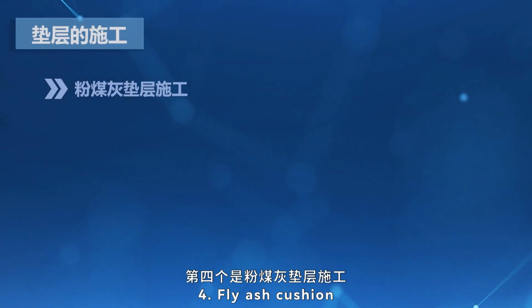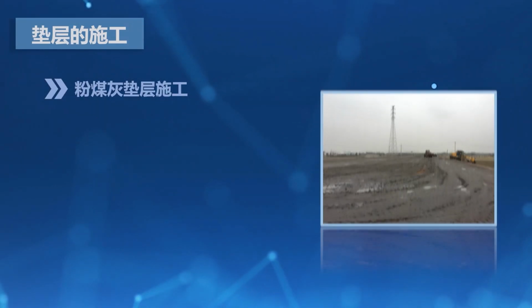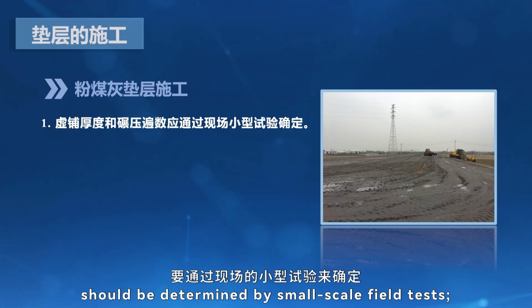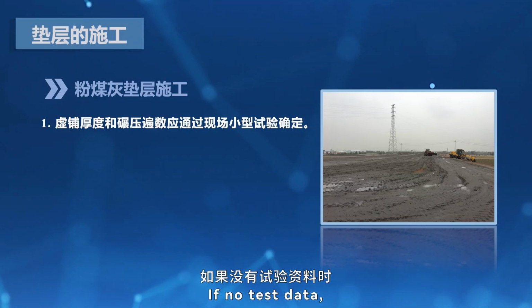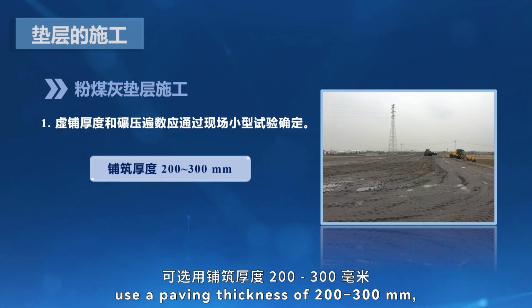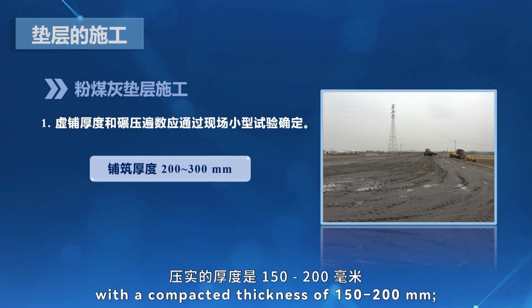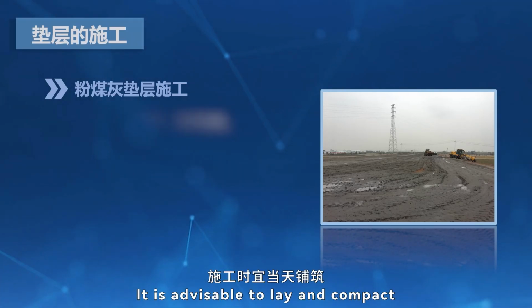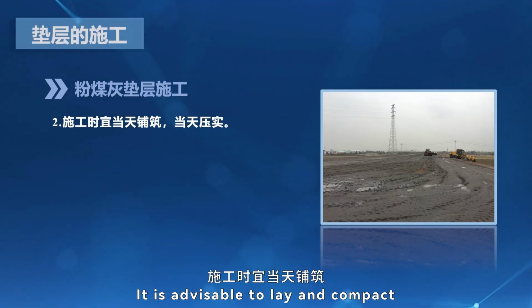4. Fly ash cushion. Loose paving thickness and rolling passes should be determined by small-scale field tests. If no test data, use a paving thickness of 200 to 300 millimeters with a compacted thickness of 150 to 200 millimeters. It is advisable to lay and compact on the same day.